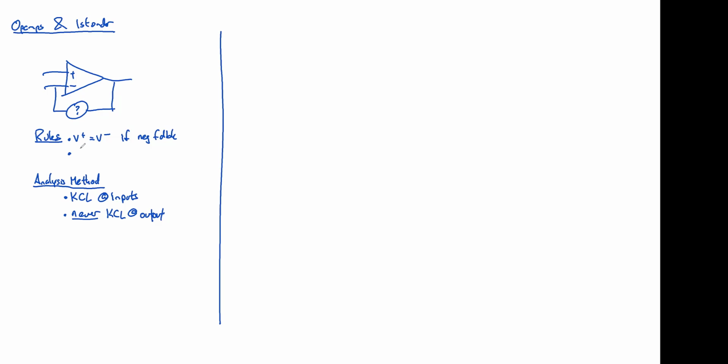No. So what Connor said is that it's got to obey KCL because the current that goes into it has to be the same as the current that goes out of it. So if you sum the two inputs, it has to be equal to the output. And that is not true. The reason that's not true for an op amp is that there are hidden power sources that power this op amp. So if you draw a super node around your op amp, that does not have to obey KCL. The entire true op amp that shows your power sources, yes, that has to obey KCL. But because those power sources are not drawn, KCL is not true for just these three leads. Was that what you said, Connor, or did I misinterpret it?